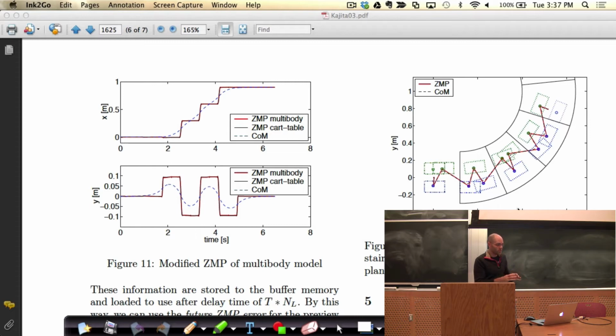The initial robots that came out had a constraint that their center of mass was always over the support polygon, and they were horrible. I mean, they moved like this, kind of painful to watch. It's called static walking. This is not a static gait. Your center of mass can move outside your support polygon, but your center of pressure does not.